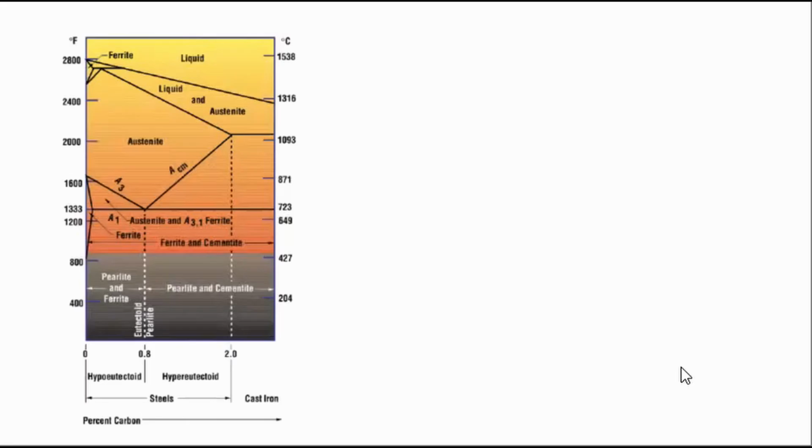understand this iron-carbon phase diagram. The question is pertaining to which one is the hardest, and this is dependent upon the rate of cooling once the metal is heated. You can see here pearlite, austenite, and ferrite forming at different temperatures. The vertical part of the graph is the temperature. Depending upon their carbon percentage, pearlite and ferrite form at this range of temperature under these carbon percentages.